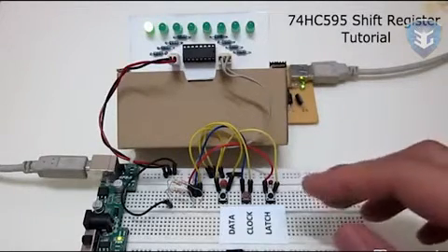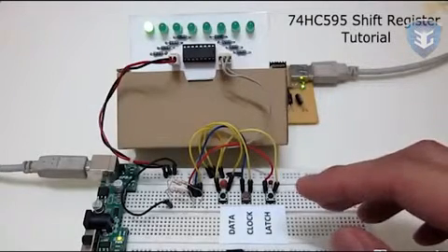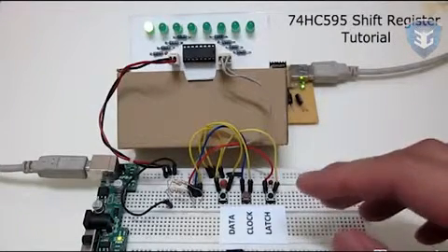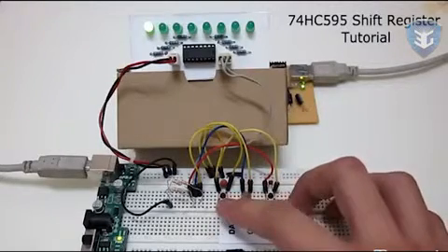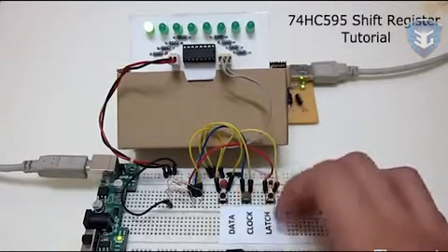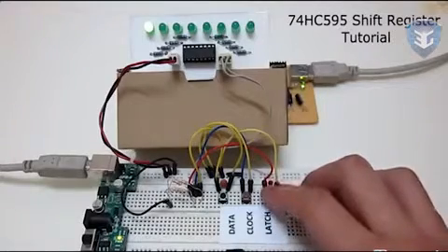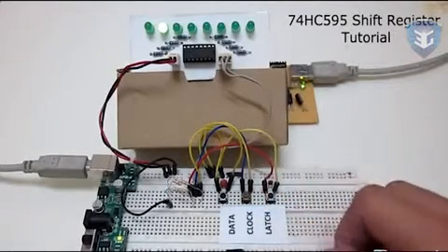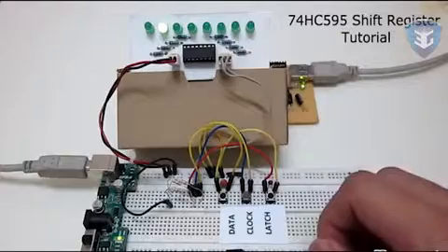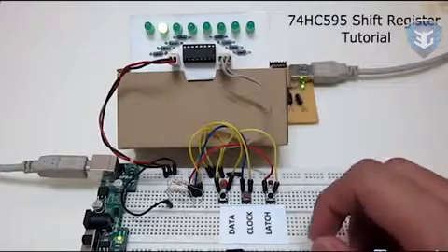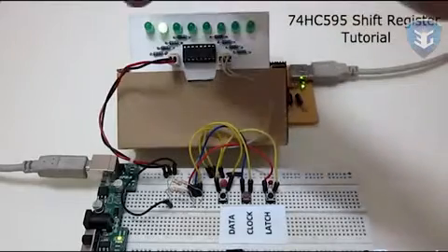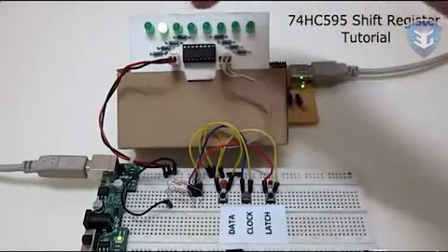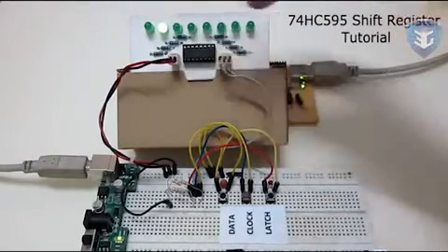So let's say I want to have the second data low. Without pressing the data line, I'll just clock in a 0 and I'll latch it in. So you can see now it's a 0. If I were to continue and proceed to clock in more data, the data will go from left to right this way.